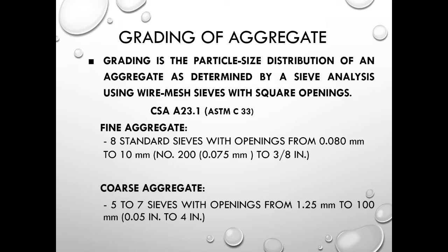One of the more common tests determined on concrete aggregate is to determine its gradation. In other words, what is the grain size distribution? Do we have a good range from small to large sizes? And again, we would test the coarse aggregate for its gradation as we would the fine aggregate. And as you noted last year in Natalie's lab, you guys did aggregate gradations. For concrete, we're looking at using CSA standards. Typically, last year you were looking at ASTM. However, for concrete in Canada, CSA A23.1 and A23.2 is followed as far as concrete aggregates or concrete materials.